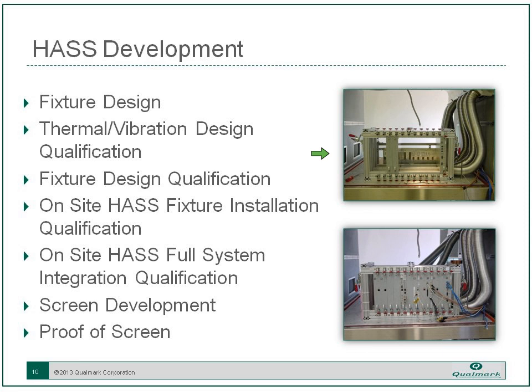With HASS, it's a little bit different. Fixture design becomes more complex. We have to make sure that we have designed a system that has equal thermal and vibration excitation for the products being tested. We do that as the fixture is designed.